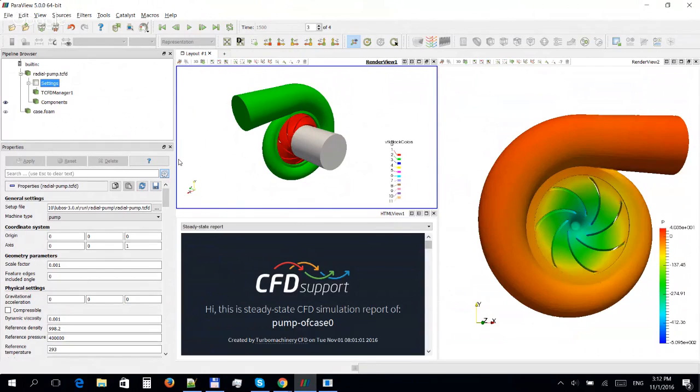When starting a new simulation, you can either write your own configuration from scratch, but of course the most effective way in CFD, and especially in OpenFOAM, is to modify an existing tutorial to the case values you want to simulate. I'll go back to the settings later in this seminar.